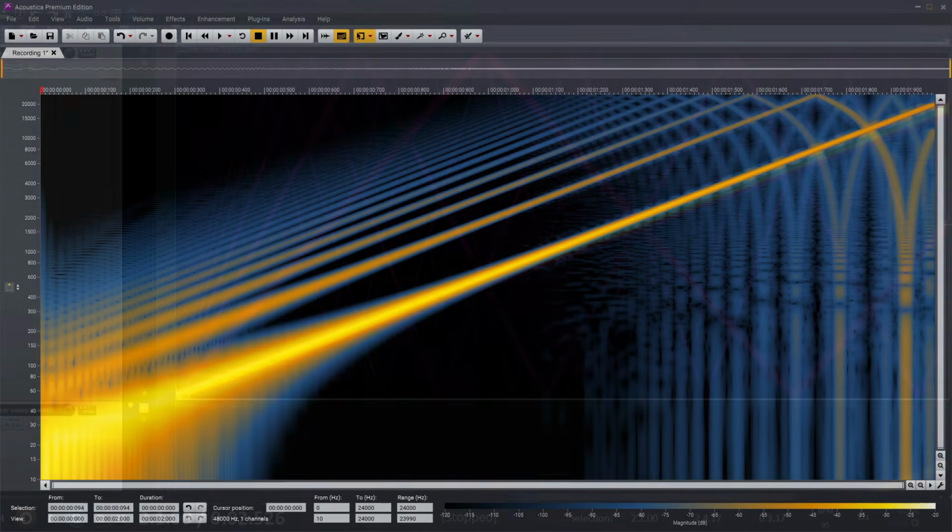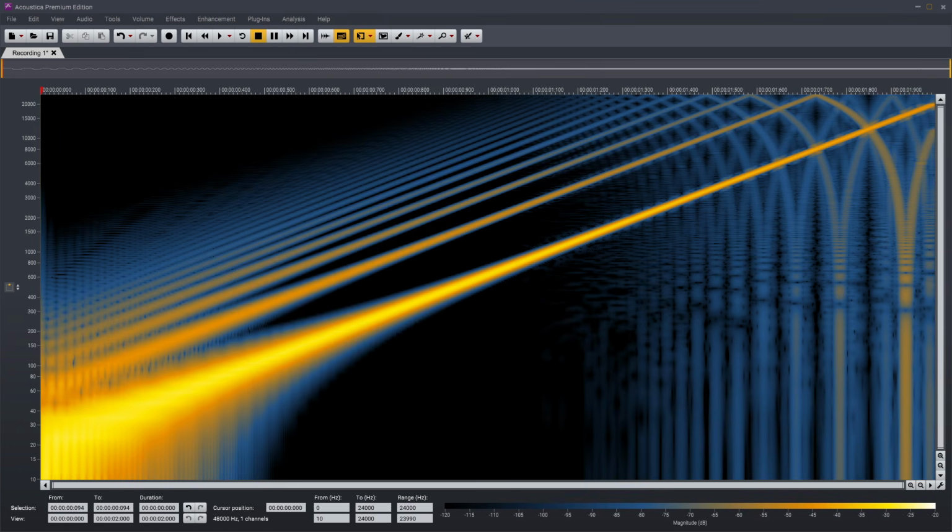Incidentally, here's how it looks if you do this test with an exponential sweep and view it on a logarithmic scale. The added harmonics now run parallel to the original sweep, which is fine, but when they reflect back down at Nyquist, the curve turns upside down, so the log scale no longer corrects the exponential sweep, and the aliasing gets this strange downward curve. This still works fine as a test. I just think it's clearer and easier to understand in the linear version.